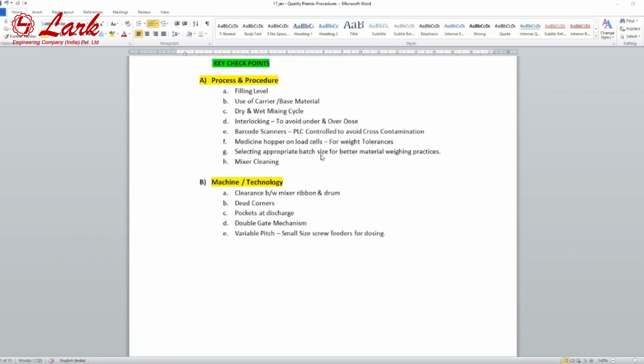And one new thing we introduce in the premix process is that we must ensure that the bag prepared for the pre-starters must go in the pre-starter batch. So how can we avoid cross-contamination, so that the pre-starter premix does not go to the finisher or the starters? We can avoid it with PLC controlled barcode scanners, very low in cost and very cost effective.